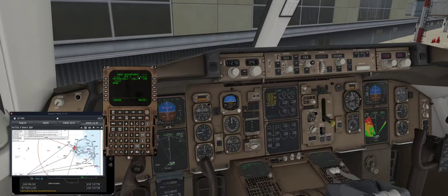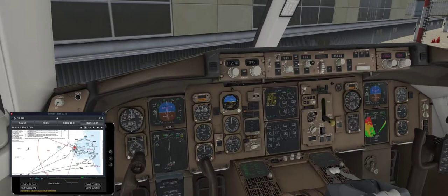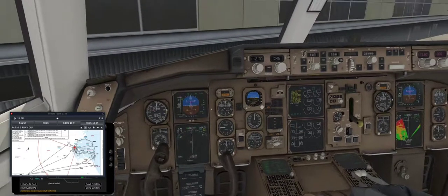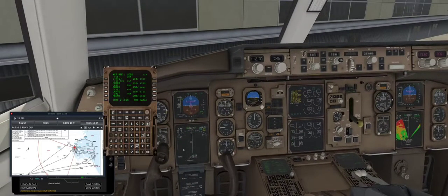But I'm going to go ahead and select it anyway to make sure that we get everything we need. Now, you'll see the legs holds some stuff, including that 520 point. I think that they said right here, then there's that 131 track to Fox. So it's all here, and it's all good, because we're going to let the autopilot follow the route, and that's probably why I couldn't engage LNAV before and VNAV, and now I can. If you can't do that at this point, then you've probably made a mistake, and more than likely the mistake you've made is going to be on the performance. One of these is probably not filled in, more than likely, or on the takeoff screen, maybe you didn't fill out your stuff here like we just did.